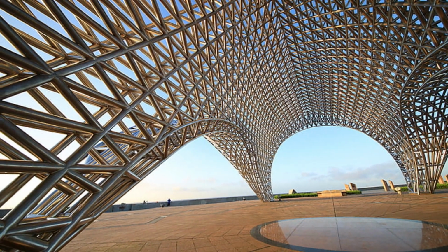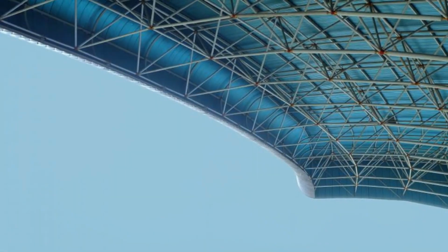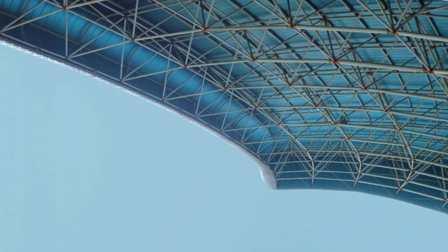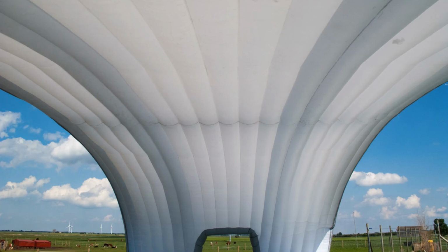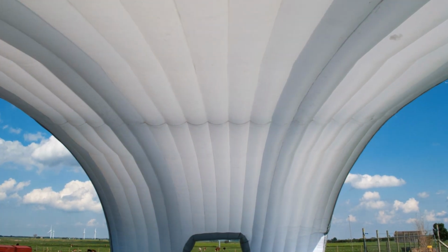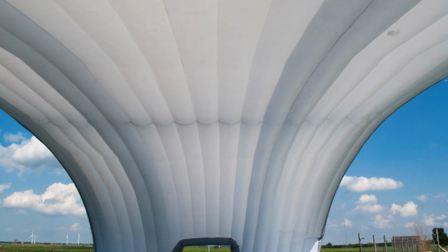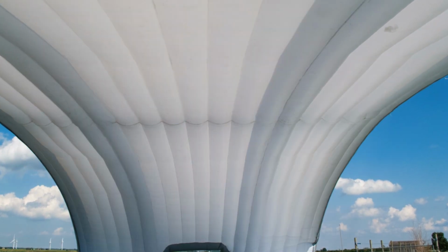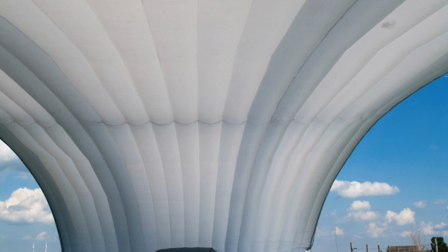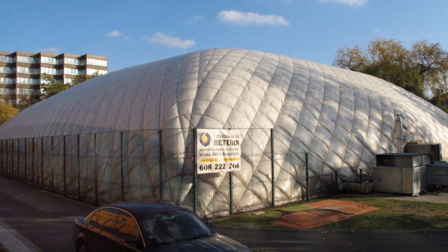We used the analogy of a gable frame one-story building to illustrate this concept, emphasizing the contrast to a post and beam system. Space frames, those three-dimensional trusses, were our next stop. We looked at how these structures, especially triangulated space frames, can span large areas without interior supports, creating versatile and open spaces. Our journey ended with inflatable structures. We talked about double-skin inflatable systems, a modern and dynamic approach to structural design that offers flexibility and portability.